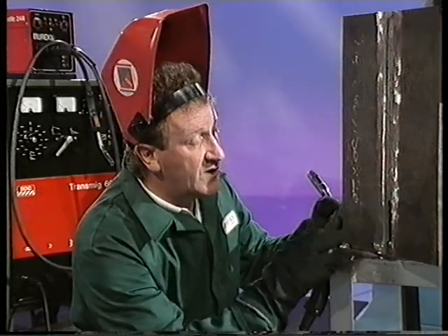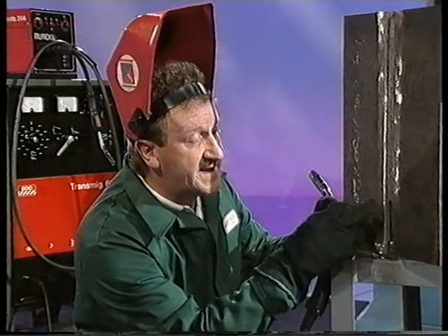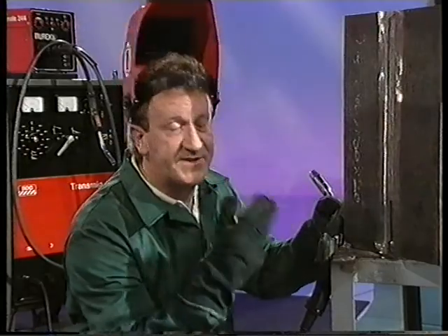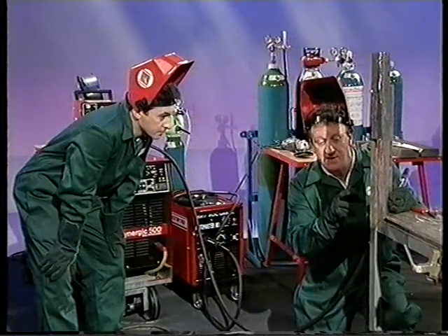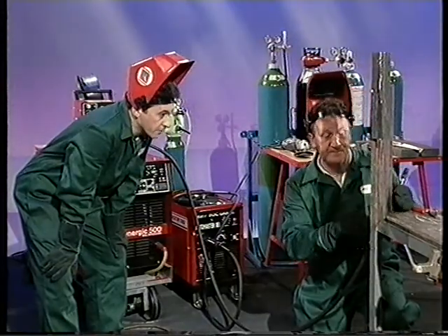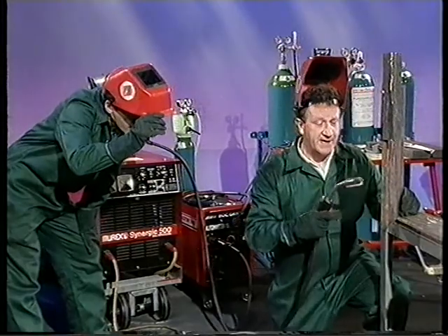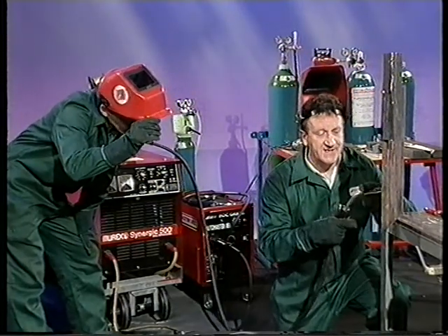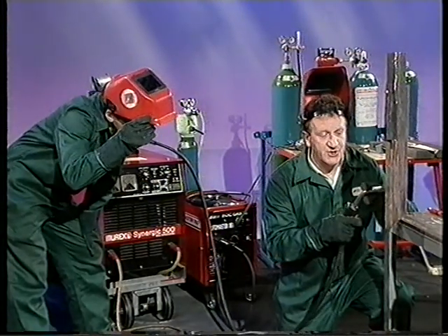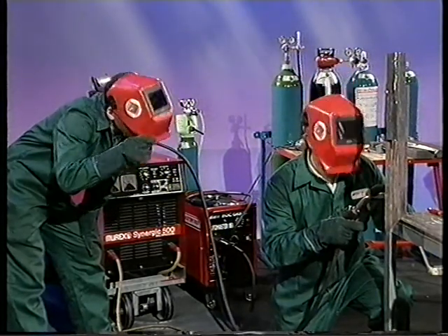When I do start the weld, I'll be starting back on the previous run so that by the time I get into that ground section, the condition is operating very, very well. This will leave a small lump on the surface, but that's no worry, we'll grind that off afterwards. It's very short stick out that we're going to be using, and I think you'll see me using just a slight side-to-side weaving motion just to ensure that I've got good fusion in at that weld. Okay. Mind your eyes.